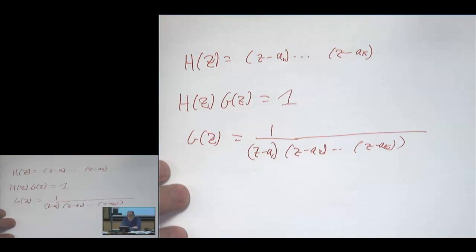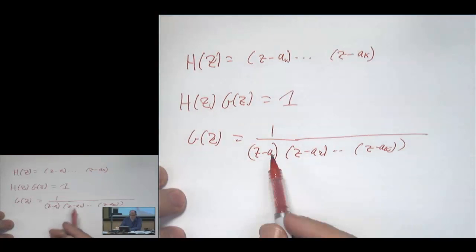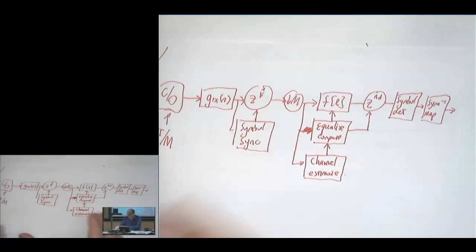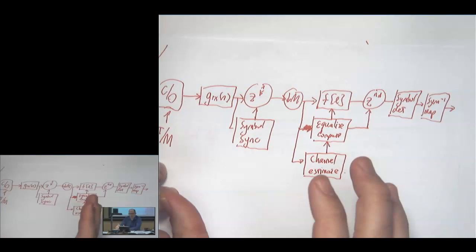And so, just as a follow-up here, we could implement an IIR equalizer, right? You wouldn't use this least squares form, but we could come up with a recursive equalizer structure. It's not impossible. It's just that the reason we typically don't do that is that we're often going to communicate using packets that are short, so maybe 100 symbols.